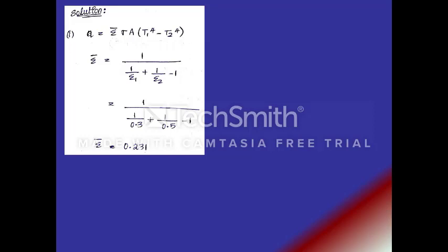First we will consider the case without radiation shield. The formula for heat transfer between two parallel plates is epsilon bar into sigma into A into (T1 power 4 minus T2 power 4). Epsilon bar for parallel plates is 1 by epsilon 1 plus 1 by epsilon 2 minus 1. Substitute epsilon 1 and epsilon 2, and you will find that epsilon bar is 0.231.